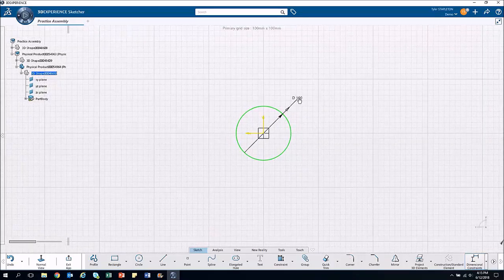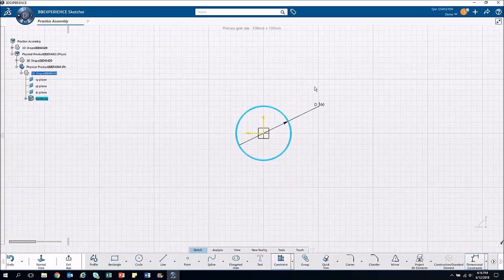And now I've defined that circle. Something I haven't shown you here, I'm going to delete that again so I can show you this. I'm going to put on another constraint, and as I'm dragging it around, it assumes I want a diameter. But I can just right click and come down to radius, and it's changed the definition into a radius, and I can leave that off to the side. Now notice I've fully defined this circle. I can no longer stretch it, no longer move it, because I've defined the center point and I've defined the radius. It's fully constrained. When something becomes fully constrained, it turns green, or the sketch turns green to indicate that.